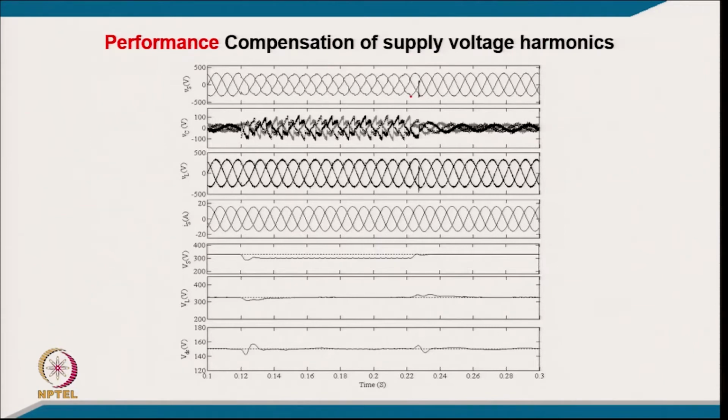You can clearly see here a typical voltage sag with harmonics in the voltage. The injected voltage and the load side voltage are balanced sinusoidal. That is the reason the load current is also balanced and sinusoidal. During this injected harmonic the fundamental is slightly reduced, but the load voltage is not affected and the DC link is also not affected.